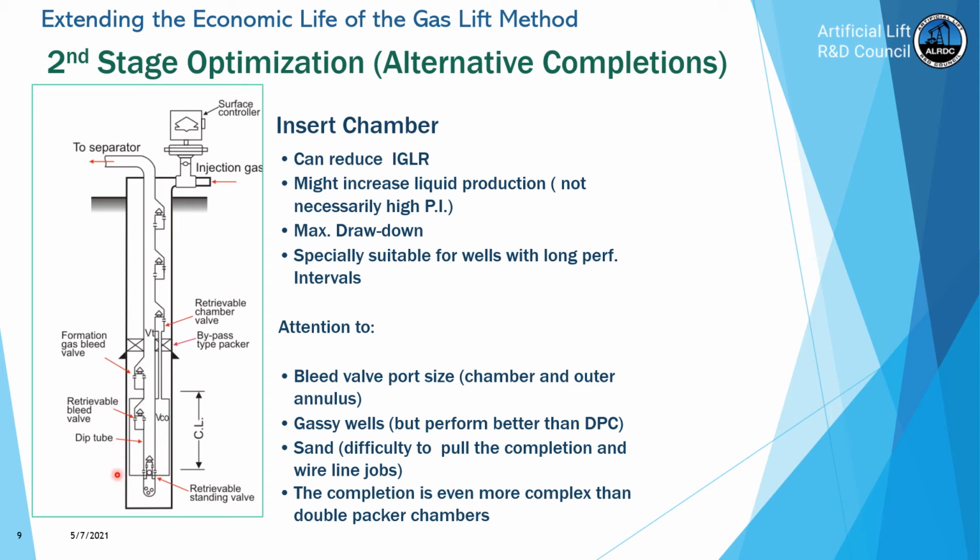With this type of arrangement, the inside of the chamber acts exactly like the double packer chamber, but now with the combination of this bleed valve here, we need to have two bleed valves, one for the annulus of the chamber itself and the other for the gas coming from the reservoir.